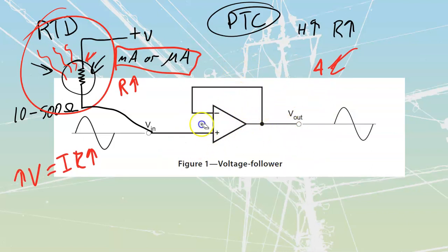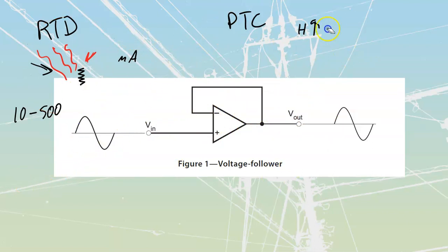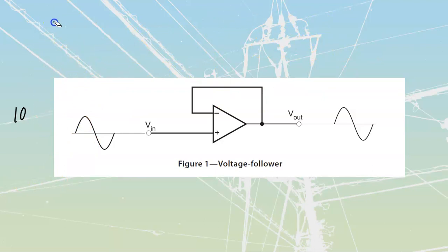In this situation that we're using it in, we are using what we refer to as feedback. Feedback is where what I have on my output is fed back into one of my input sides over here. And so we're always going to be working to build this thing into balance, because as this voltage over here goes up, then it is going to go up in relationship to whatever this V out was. We'll start with this V out at 0. If this voltage goes up, that means that this voltage over here, because this was at a value of 0, tracing it through, would also be seen as more positive. Therefore, this would start to rise up as well.